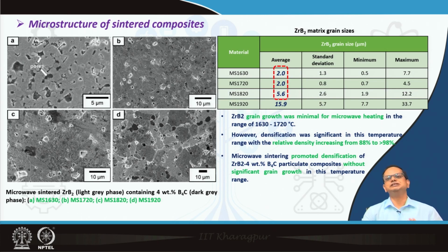Now, if the temperature of sintering is higher, then the temperature difference during cooling is obviously higher, and that leads to an even higher amount of residual stress. So, we can say as we increase the temperature, at the interface there will be a higher amount of residual stress, and as the residual stress crosses a limit, a critical value, it would lead to delamination at the interface, or cracking, formation of fine cracks or micro cracks at the interface in this material.